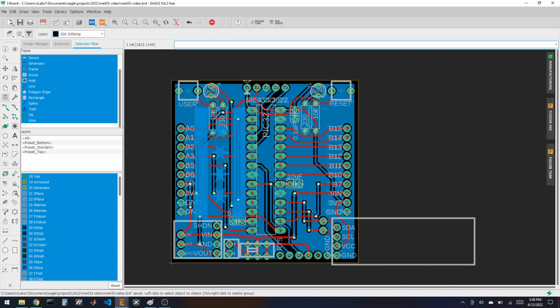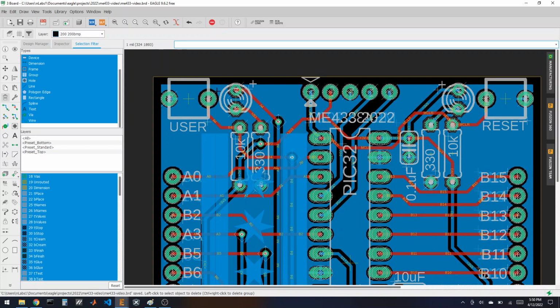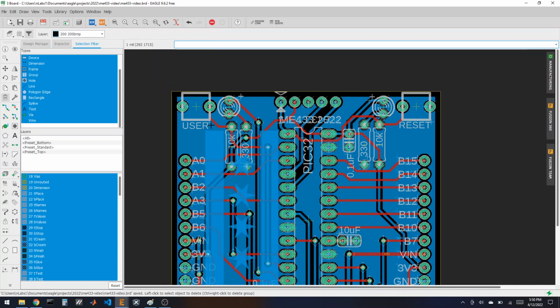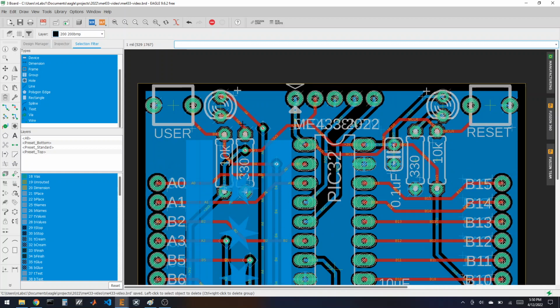I can turn this into Gerber files, and then we should double check what the Gerber files look like. But if you really wanted to go crazy, we've got space over here, we've got space over here. We could put more vias in there, and we could break out more pins that maybe you want. So, for instance, the B4 and A4 pins for the user button and the user LED, maybe we don't want to solder those in, and we'd rather put other components in there. So we could break out pin A4 and B4. Why don't we do that just for fun? Let's do it in a way where we don't have to change the schematic.